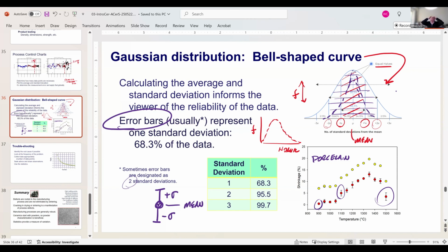I recommend that when you measure some things, usually 5 data points is sufficient. You may decide that you want to measure more specimens to figure out what the range of that data is in general. And then you can establish a standard deviation that applies to all your measurements. That's not unreasonable. Density measurements, shrinkage measurements tend to be remarkably consistent. Therefore, the standard deviations are small. So you might be able to measure just a few samples or 5 samples and get a reasonable number.